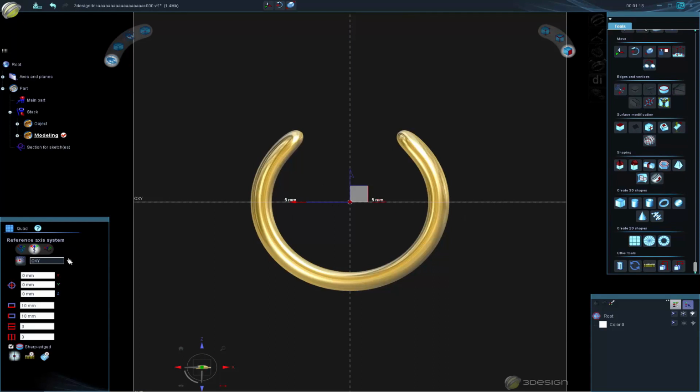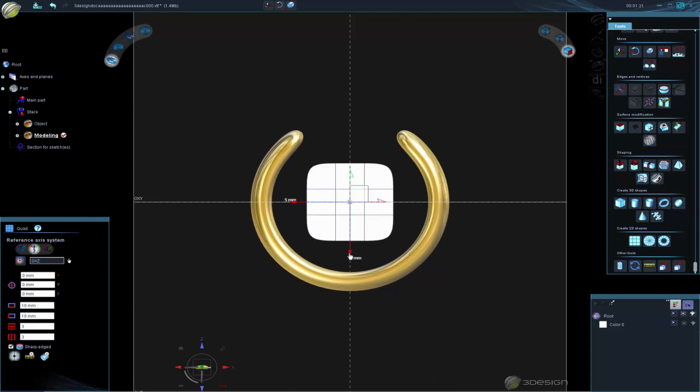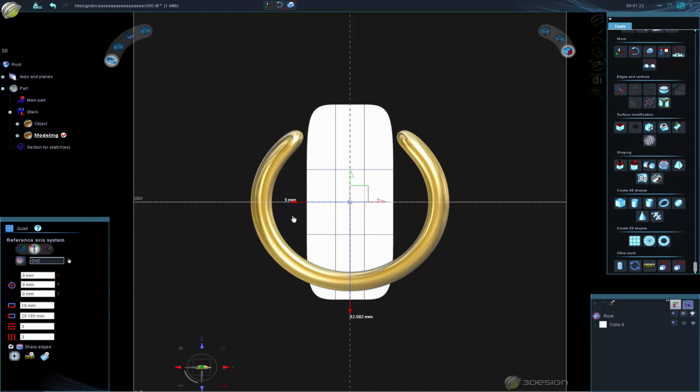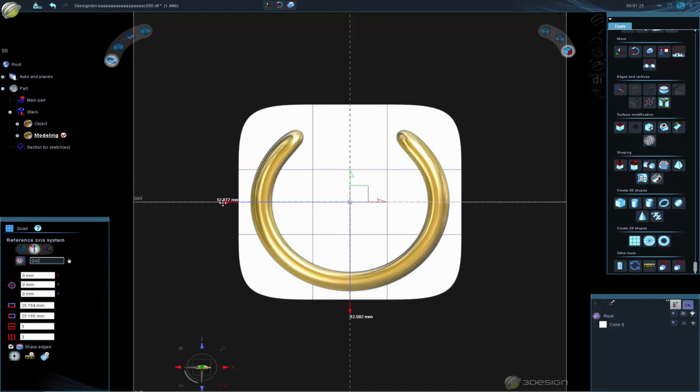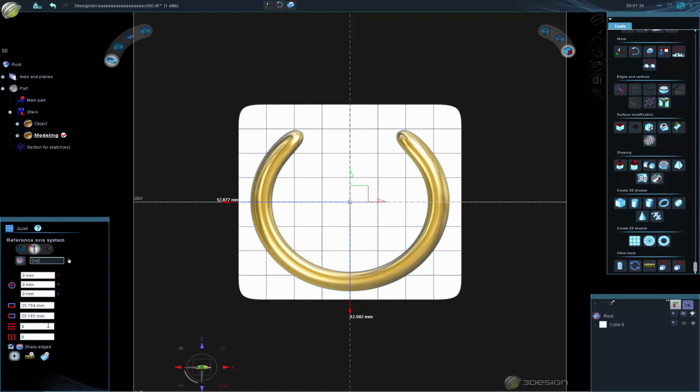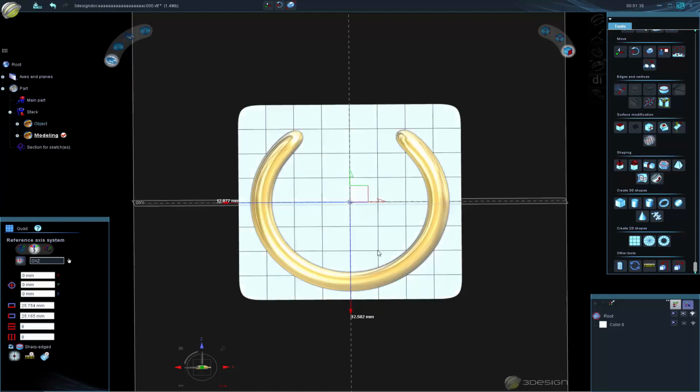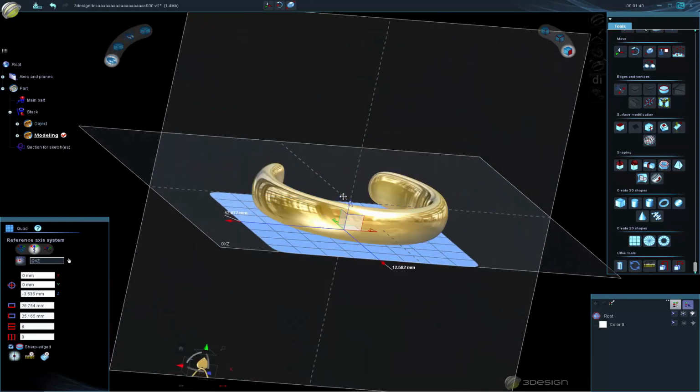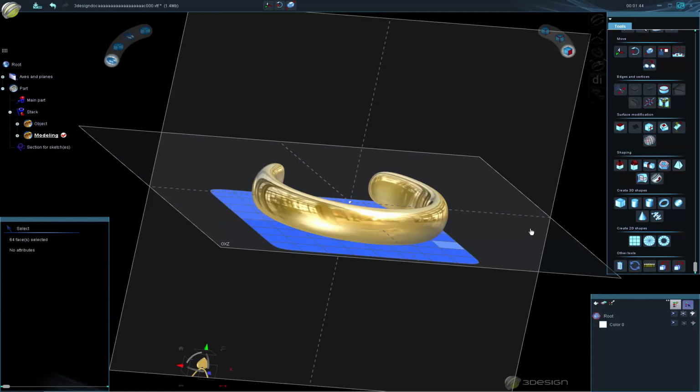So I'm going to start with a quad, which is a basic 2D mesh. Just kind of stretch this out around my ring. Some things to keep in mind is make sure your mesh completely encompasses your object. Everything, your object needs to be inside the mesh. Okay, add some subdivisions here. And I'm just going to move this to one side of the ring. And then select all the faces and shell it. Simple, quick way to make a mesh around this.